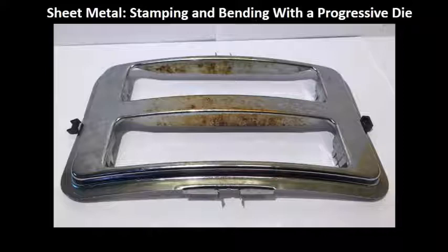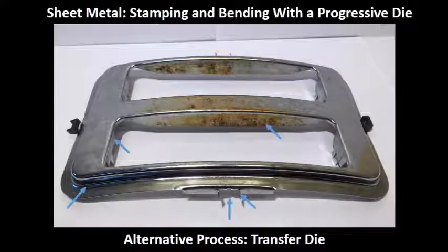The toaster lid is made from stainless steel sheet metal, and evidence suggests that a progressive die was used to manufacture the component. The progressive die used to make this part used a combination of shearing, bending, and stamping operations. The first step in the conveyor was the punching of the slots and the tabs. The steps following the punching consisted of several bending processes that occurred along the conveyor.